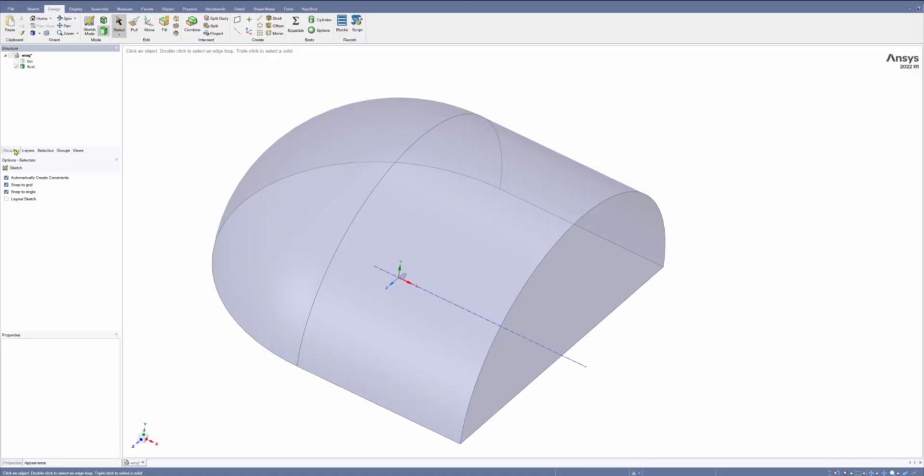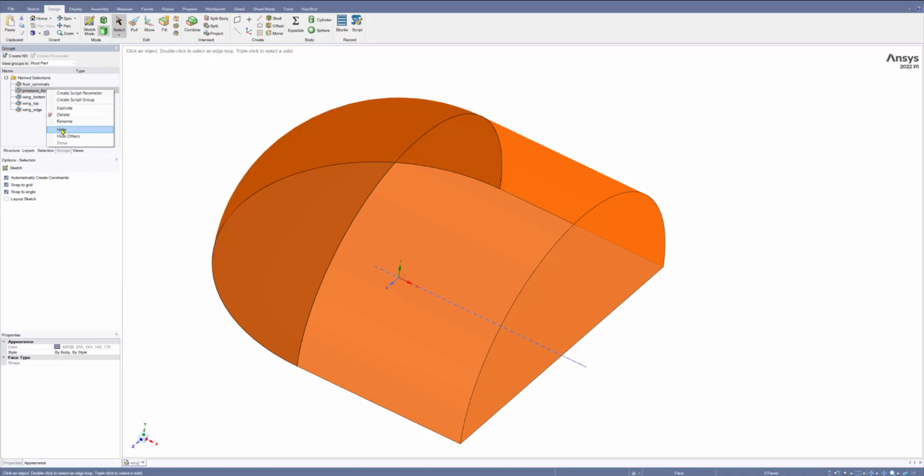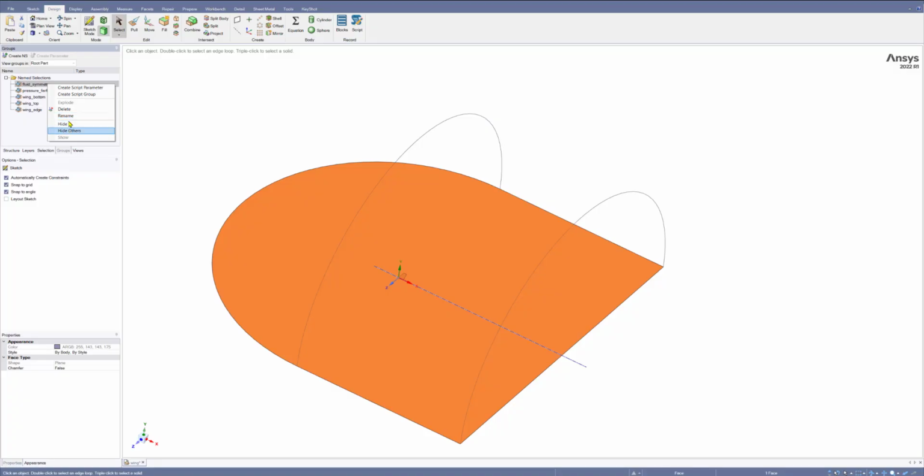We call this the fluid in general, and we have some groups here as our boundary conditions. We have a symmetry at the bottom and this pressure far field around the airfoil. So I can hide this one and also this symmetry.